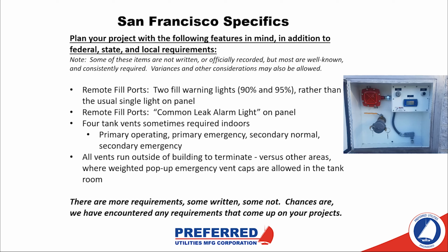Sometimes in San Francisco, we have encountered situations where they've required 4 tank vents for tanks that are indoors. We have also encountered the last point there, which is that all vents run outside the building to terminate, versus other areas where weighted pop-up emergency vent caps are allowed indoors. So when dealing with vents in San Francisco, it can be a little different than is allowed in other locations, including running not only 3 but 4 vents and running them all the way outside. Those vents all, of course, need to terminate 12 feet above local grade.